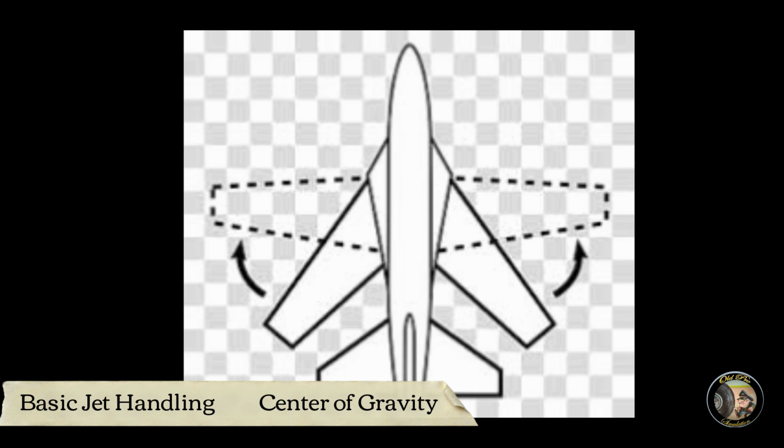However, it gets more complicated when we look at a swept-wing aircraft. As you can see by the illustration, the swept-wing aircraft, its aerodynamic center on any given point on the wing moves aft due to the wing sweep. This makes determining where we need to put the center of gravity in relationship to the aircraft much more difficult, because where is the center of lift anyway?